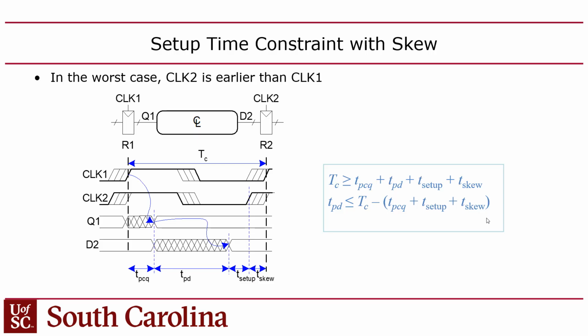So that clock skew is kind of a worst case skew. It's the amount of time difference between the clock rising edge nearest the clock pin and the clock rising edge farthest away from the clock pin, as compared to whatever the clock period is, right?